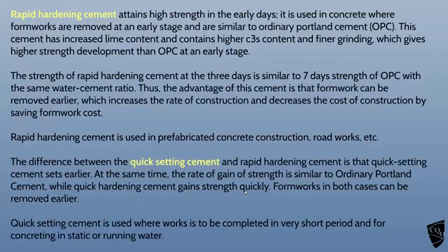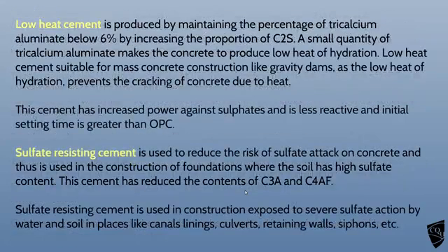Rapid hardening cement, well, I don't need to say anything about that. You can read that. It just sets very quickly. The difference between quick setting cement and rapid hardening is that quick setting sets earlier but takes longer to harden. I know, it's confusing.